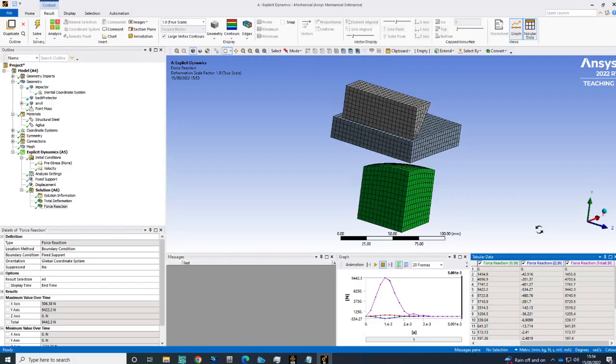So are you happy with this? Do you think that this is a level 1 back protector? Well, something to be extremely careful about is that we use symmetry. So we cut our model in a quarter. Hence, we need to multiply this force by a factor of 4. Therefore, the force here is around 40 kilonewtons, which is obviously way above even the higher value for level 1, which was 18 kilonewtons. So obviously, a single layer of Agilis 2 centimeters thick is not going to pass this